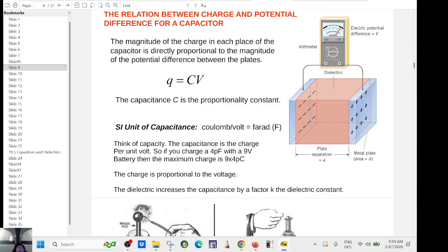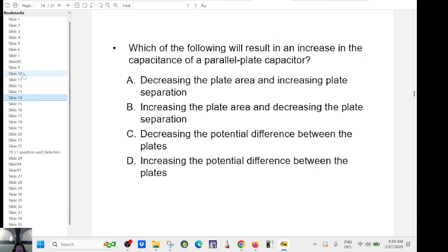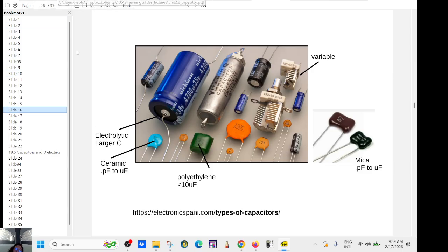Yes, so this is capacitance. It's a property of each capacitor. I don't know if I have pictures of capacitors somewhere here. For example, this one has 4700 microfarad. So it's like a blueprint. It tells you how much charge it can hold. And the 35 volt means you should not go over 35 volt, because otherwise, believe me, it's popping in your face. And it's not very cool because it's full of acidic stuff.